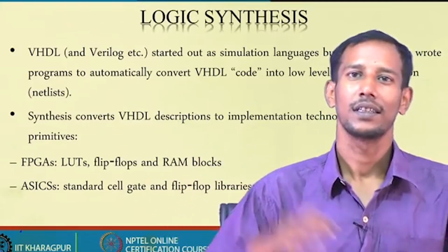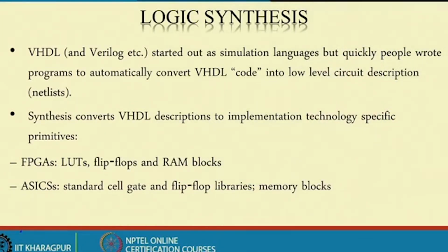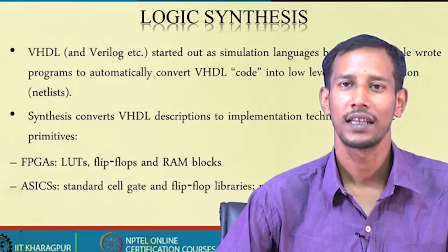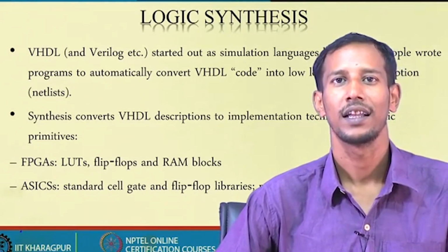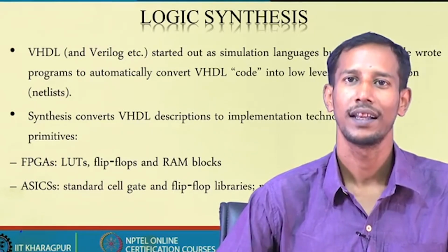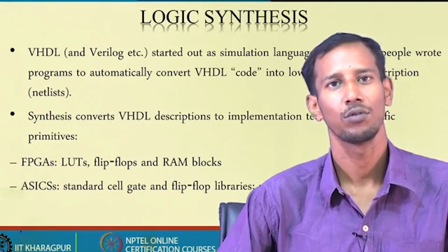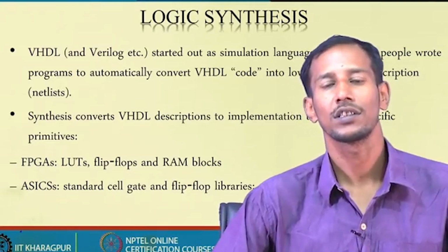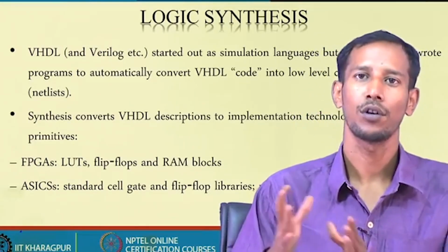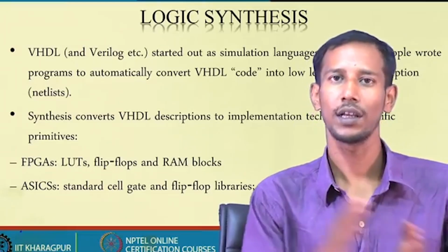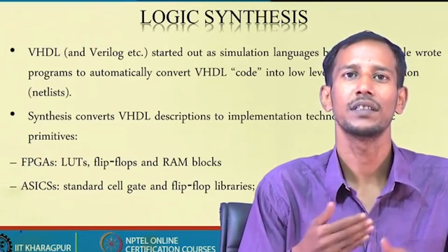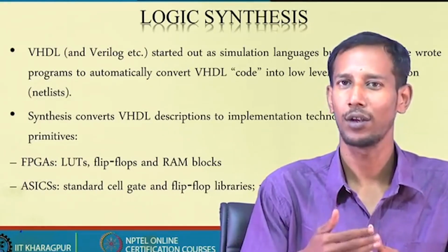Yesterday we have seen that the FPGA design style has to start with specification, then the RTL specification or detail design, then function simulation, and then synthesis, then timing simulation, and then you can go for the device programming part. And what I said is that logic synthesis is the part for converting from the logical expression to the gate level netlist.